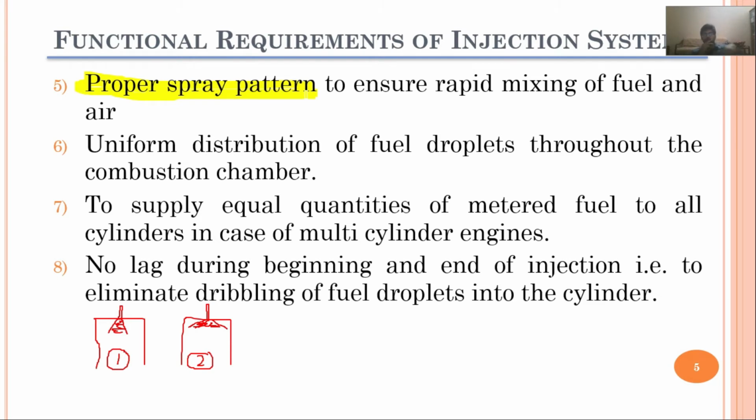Similarly, it also has to ensure the uniform distribution of fuel droplets throughout the combustion chamber, and this is ensured by having a proper spray pattern. Now moving forward, for example, when we have a multi-cylinder engine, your fuel injection system would not only have to deal with the above mentioned functions.